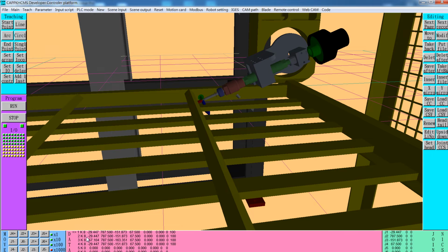The first line and the second line have the same data, and then change the coordinates to let the y-axis vertical. This point doesn't move, just turning. Then we have to use the Cartesian coordinate system. We have to change RY from 157 to 90 degrees.